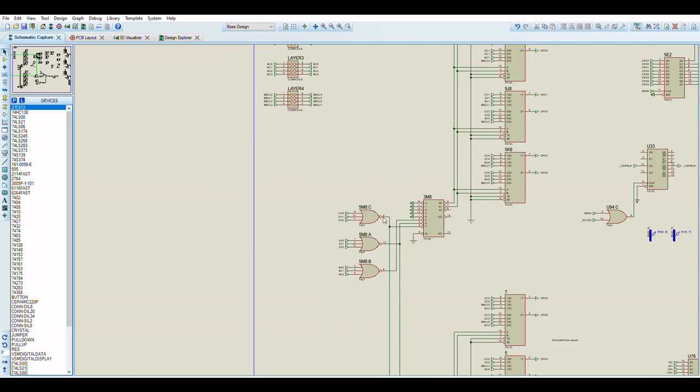And we have 3 pixel transparency tests, which use the bottom 3 bits of the pixel from each of these headers. So 3 bits, 3 bit planes, up to 8 colors per character, sprite, or tile. This basically says, is it transparent?